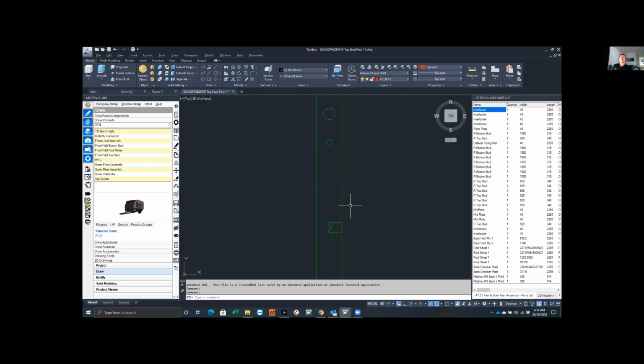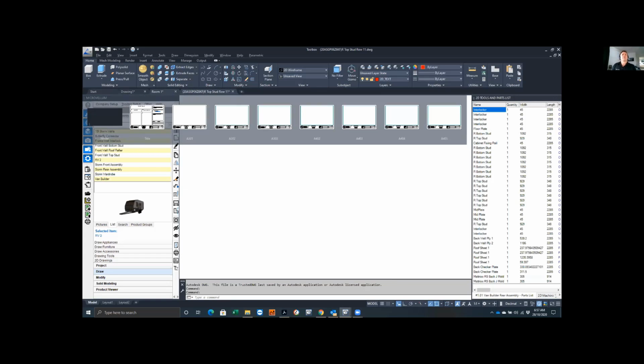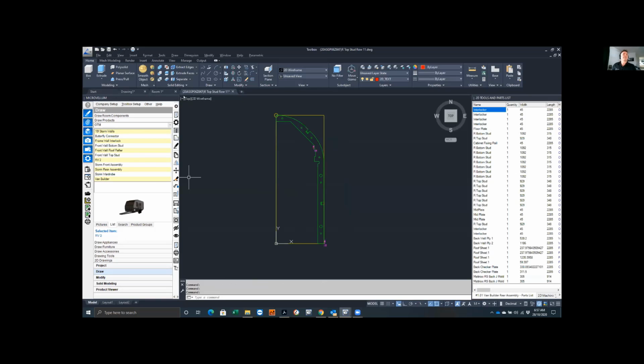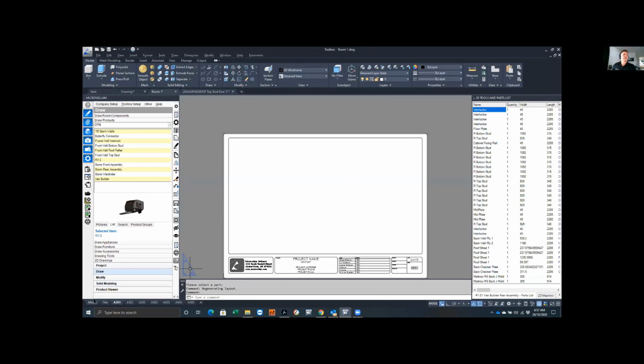The router can just come in and out rather than pulling up and down. It was just an easier process for us, with less blowout as well, and easier on the cutters, because this lightweight ply is pretty hard on cutters. So that's worked really well. So these are just parts that are programmed with polylines, and it's all formula driven, but go back to the product.